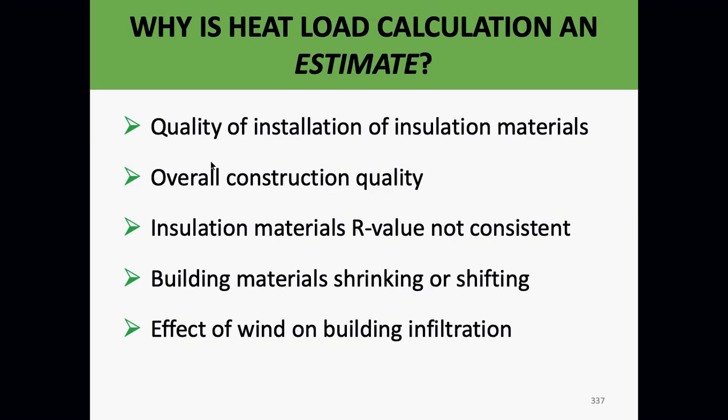If the wind is blowing on the side of the house with the crack in the brick, it's going to blow cold air into the wall spaces, and in turn the wall will feel cold and absorb the heat in the building. Gaps, paths for leakage.